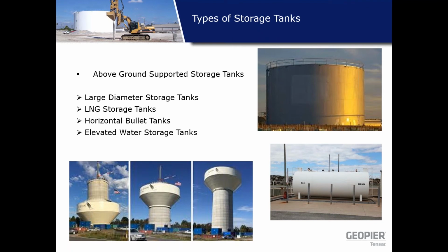These tanks exert heavy loads and they're typically designed for about half mega gallon to 2 mega gallon water carrying capacity, and generally the overturning moment governs the design. The foundations for these tanks are generally ring wall foundations embedded about 5 to 6 feet or sometimes 10 feet below the ground.